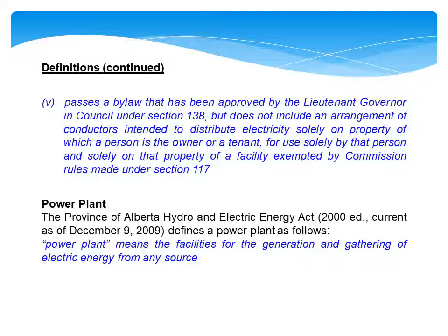Requirements for overhead and underground systems are included in Sections 10 and 12 of the Alberta Electrical Utility Code. The code also identifies 2 standards from the Canadian Standards Association, which must be referenced by the code users for comprehensive and complete results. The reference standards are CSA Standard C22.3 No. 1-15 Overhead Systems, and CSA Standard C22.3 No. 7-15 Underground Systems.